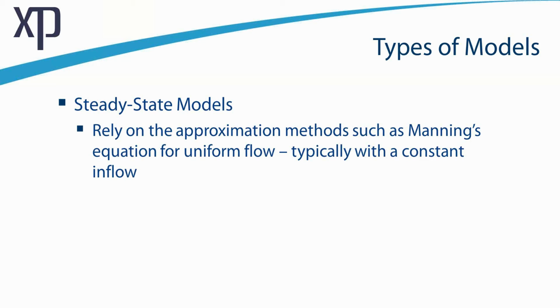And for those of you who aren't familiar with the kinematic wave equation, the pure simplification there is that the energy grade, which I'll talk about in a moment, is equivalent to the slope, or the bed slope, and that's the fundamental simplification of that equation.